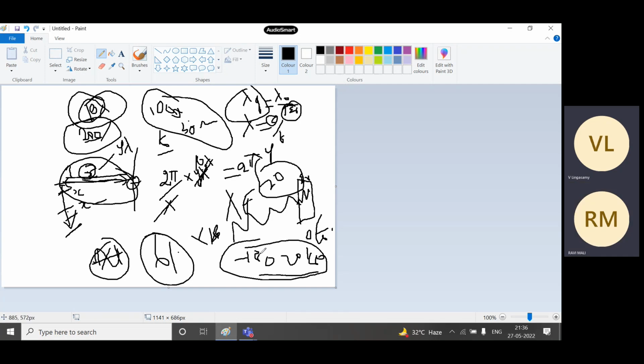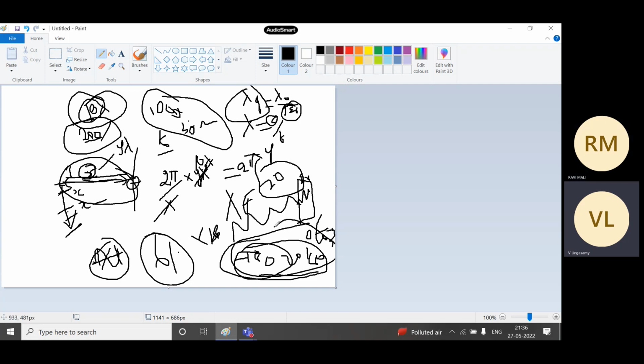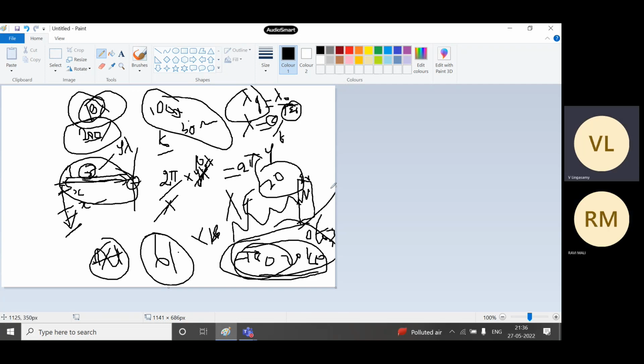Okay. So instead of minus 180, I will add 360. Then you will get the 0 to 360 degree value. Okay. Now, this is one way of doing your element phase. You have to do this wrapping and unwrapping. Nowadays, CST also has that inbuilt. So you just click on phase unwrap, then it will unwrap.